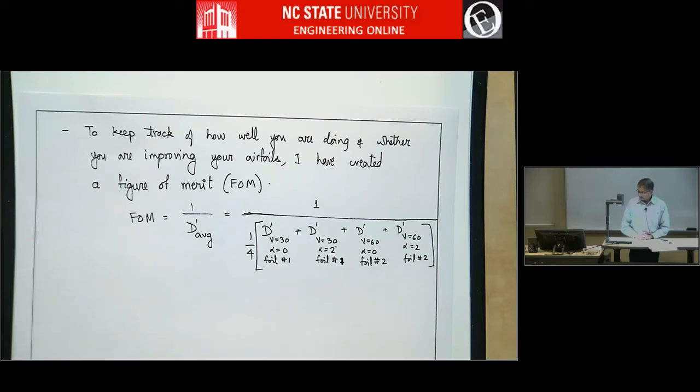Anyway, so there is no one procedure, but I will give a suggested procedure so that at least you have some outline if you want to follow that. But there is also a lot of room for your own design intuition. And you can see, for example, if laminar separation bubbles are occurring, then you can adjust the velocity distribution and all that. And we'll also move away from a 4-segment airfoil. The 4-segment airfoil is basically for demonstration purposes. In reality, you will have more segments which will give you more control over velocity distributions.